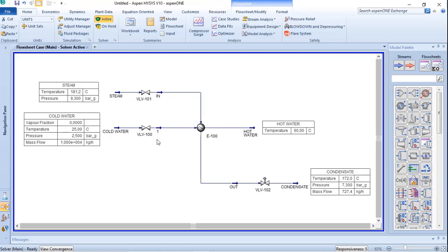So in this case, you need to go to the control valve datasheet and verify the CV and add it to your process simulation. The same for the heat exchanger. Here I simulated a theoretical one for the example, but the best results that you can have in your dynamic simulation is getting real information from equipment and adding that to your process simulation.